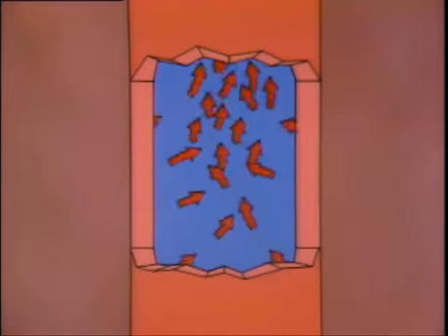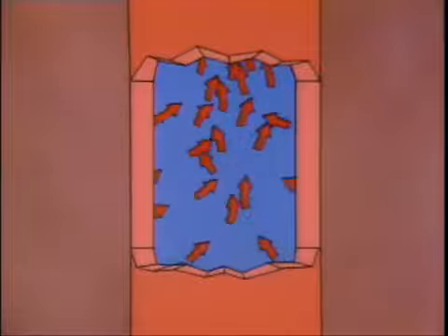Convection heat transfer also occurs as the warmer water mixes with cooler water. When enough heat has been transferred to raise the water temperature to the boiling point, steam is produced. When a boiler is working properly, the heat produced by the burning fuel will be readily transferred to the water in the tubes. However, there are problems that can interfere with heat transfer. One of these problems is a condition called scale.